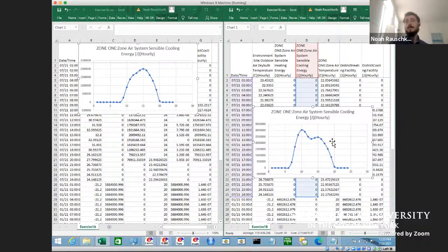And when people talk about things like passive house design, one of the big staples of designing a passive house building is you don't have any south-facing windows that aren't fully shaded in the summer. Because if I had a south-facing window, I get a big peak right in the middle of the day, and that's a lot of energy. So if you have south-facing windows, they have to be fully shaded. And the same thing with west-facing windows. That's the other time where you would typically have a peak. You have to be careful with those.